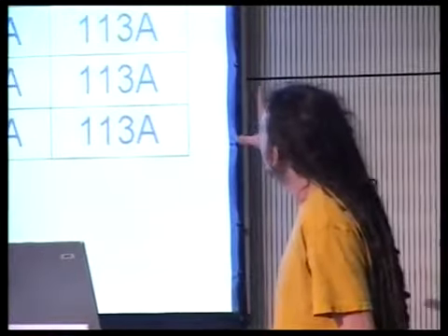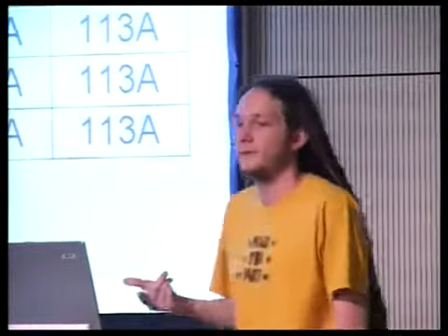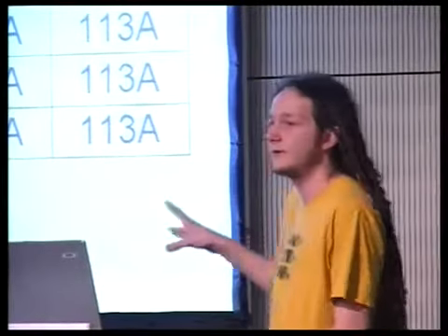So in this case, by using the interrupt vector table, every complicated firmware image will automatically have its own sort of unique password. And the manufacturer will have a copy of that password, but no one else will. And the compiler can't not set the password. So when you have all of these fly-by-night, hey, let's make an MSP430 compiler companies, they all, by the very nature of the chip, have to make a unique password for each image.